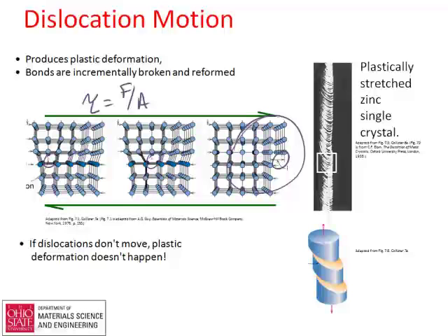If the dislocations don't move, you'll get reversible deformation that's just based on bond stretching. But if the dislocations do move, you get this permanent deformation, and you can see these offsets, and that's what causes the permanent deformation. Okay, as I mentioned briefly before, it's beyond the scope of this. There's a relationship between shear stress and normal stress, and here's, for example, if I take a zinc crystal, put a normal stress on it, stress is force over area. That can also turn into some shear stresses. You can see those offsets, and that's what we end up getting, and that's all the result of dislocation motion.